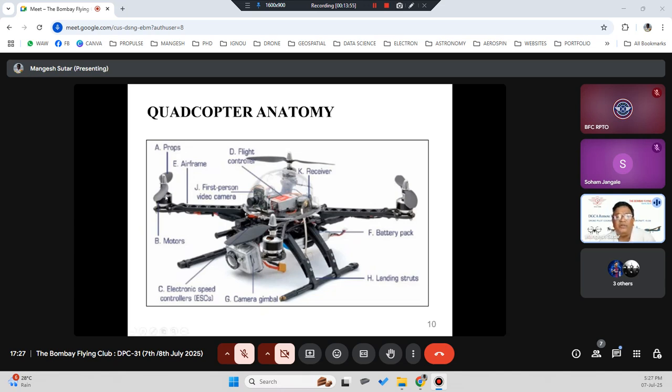Then you have motors from T-Motor, Hobbywing, and third-party motors are also available. Similarly, along with the motor, you can get matching propellers. You can't just take a motor and choose whatever propellers. A lot of the time the motor defines what kind of propellers are tested and suited for it. Similarly, with the motor you need a matching ESC, that is an electronic speed controller. It's a regulator which controls the speed of the motor as required.